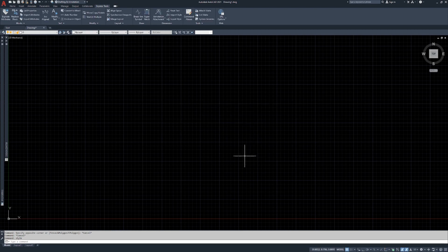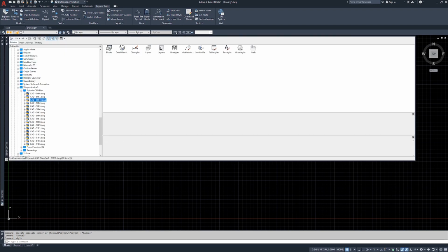Now this, like I said, was going to be quick, but there are a lot of people that don't even know this exists. People will go into a drawing and then they'll have to block something out that's on the text style that they want. When you block text out, sometimes it'll pull in the style that's associated with that text. Other times it'll say, I don't really care to carry that over for you. Design Center is the fast way to pick through drawings.